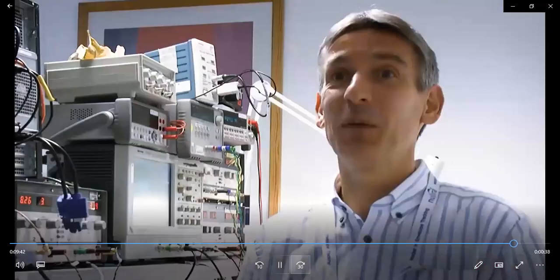Make sure that the spectrum options match your application requirements. I would advise to look a little bit beyond the traditional RF specifications like spurious free dynamic range or third order intermod, and look at the capabilities for discovering transient signals, triggering on them, capturing them, and then doing multi-lane analysis. My top tip would be to ensure that you have all the latest software and firmware upgrades on your instruments to ensure that you're picking up all of the latest facilities that are available, possibly for free.